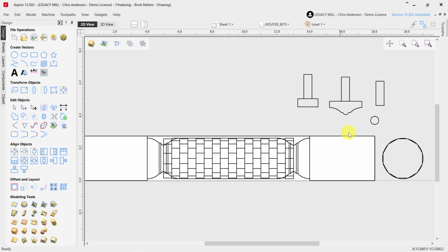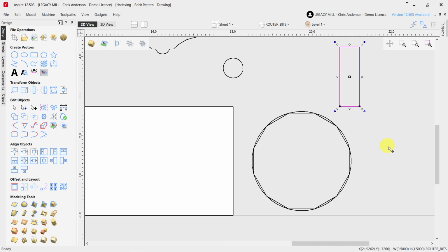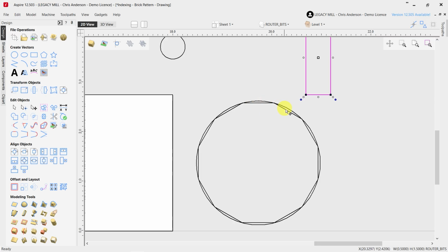Okay. Now what this is going to do is the cutter is going to approach at the starting position. It's going to plunge down to the first flat section, but it's going to be cutting across the material while the material is stationary. And to help show that even better, the cross-section view helps represent that. So if you look here, we have these flat sections, again, evenly spaced around the circumference. And this is going to cut as deep as that flat section, but it's not going to do so right on the top of the material. It's actually going to be starting off the material just to the side.